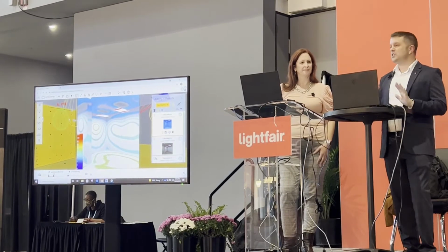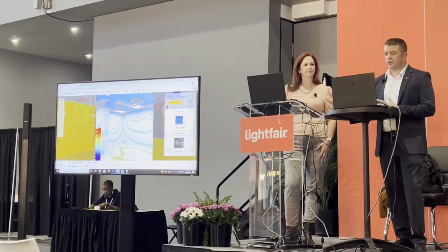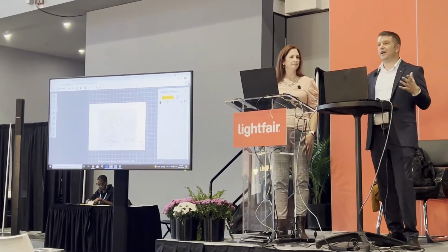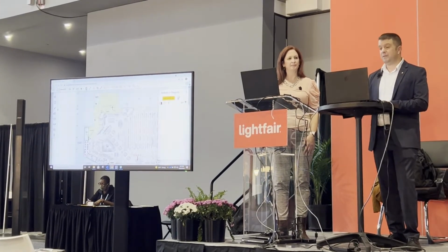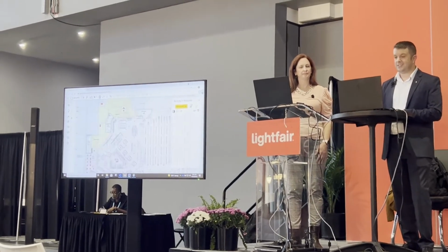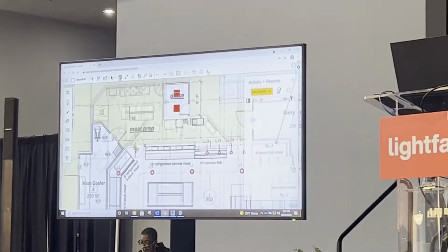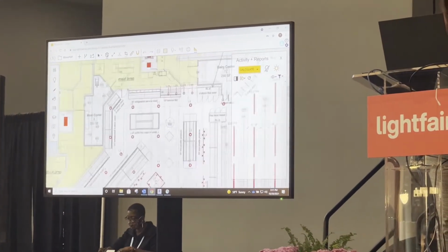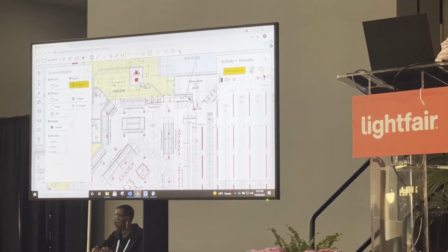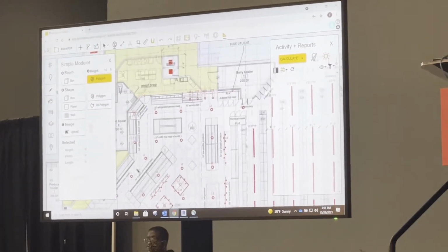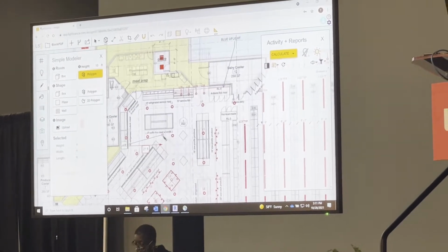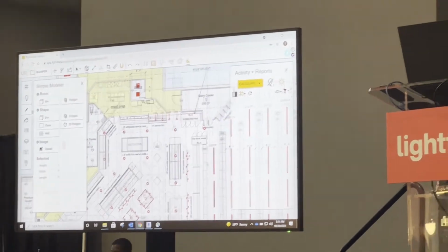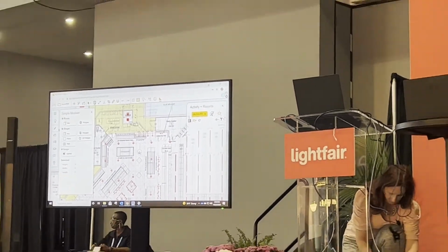So this is one workflow, right? And another workflow you might have would be, maybe you just want to bring in a PDF, right? You don't have drawings, you don't have a CAD background, whatever. You can just bring a PDF in, click measure and scale this thing, measure a door. It'll say, I think that's 1.5 feet, it's actually 3 feet, boom, this is scaled. Now I can go over, create my rooms, do a polygon. I'm not gonna draw all this for you, this is a complicated space, but hopefully by now you get the idea, right? So that's one kind of workflow, that's that standalone workflow, but there's another workflow.